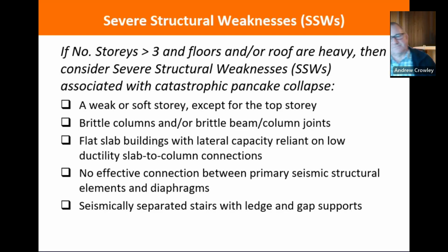So, is the stair likely to fall off? Another issue with stairs, though, is sometimes the stairs are supported halfway up a masonry wall. So a seismic event will then put lateral loads out of plane on a masonry wall, which can lead to its collapse, which will lead to the collapse of the stair.